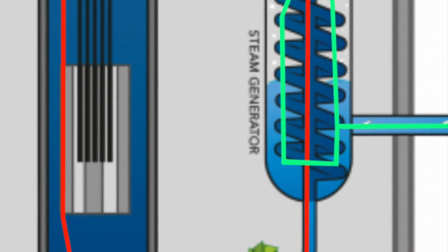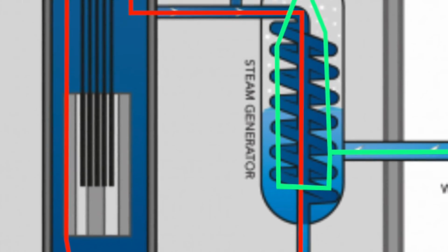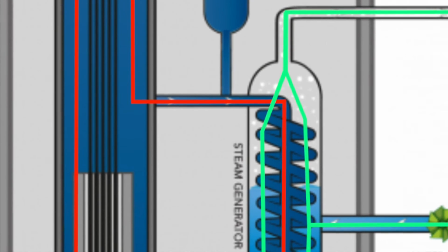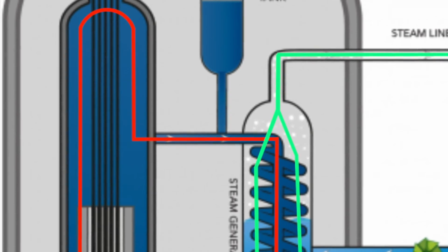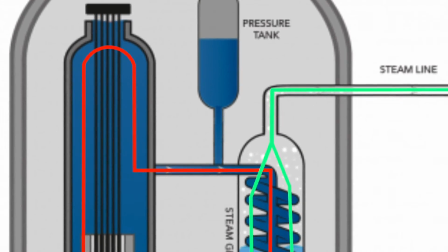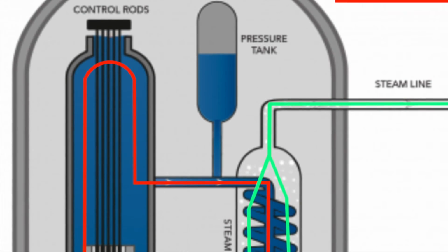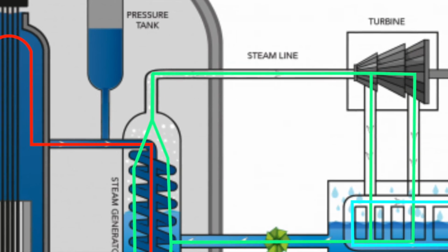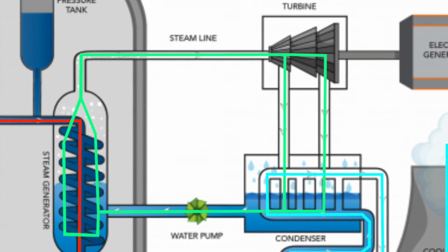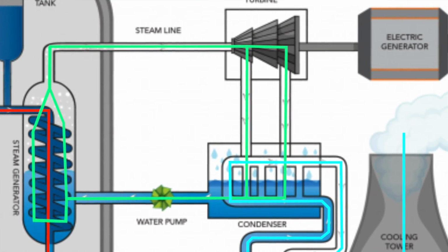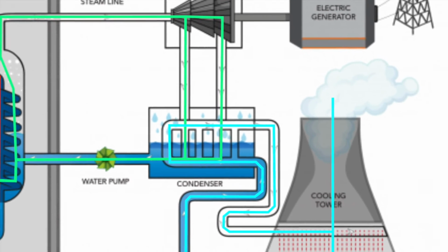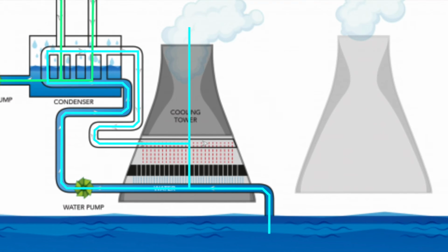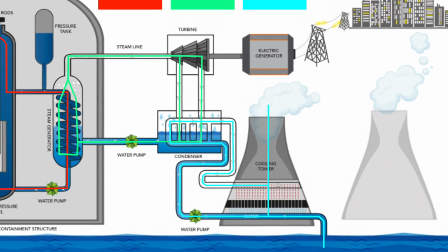The heat provided by nuclear fission would then go into the primary circuit. After the primary circuit gets heated up, it moves along this pathway and goes to the secondary circuit and heats it up, while the secondary circuit becomes steam, pushing the turbine and generating electricity. It then finally gets cooled down by the tertiary circuit, which comes from a river or something like that. So it comes back, and the whole cycle continues again and again.